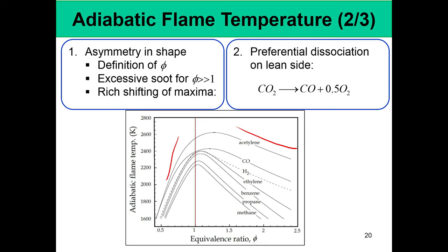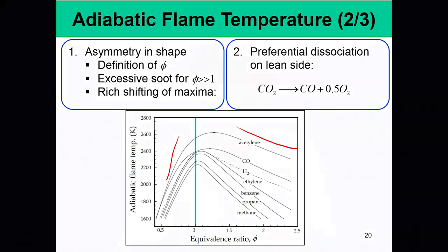Of course, you must also note that there is a lot of soot if you burn fuel rich, because of the unburned hydrocarbons and particles that are being formed, and this CO. There is some ring structure formation, and then there is polymerization, and then you form soot. That is why fuel rich combustion is very much unwanted.